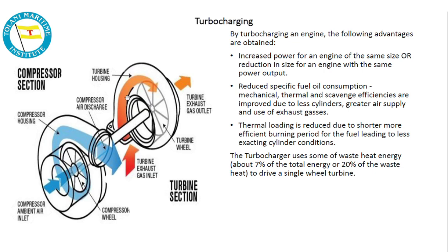Now turbine side is actually which has suction for the hot air, the exhaust gases. The exhaust gases enter this turbine side and then exit from here. Now this exhaust gas, which is in motion with a very high temperature, rotates the turbine blade. The turbine blade is associated with the shaft, and we are going to see all these things in detail.